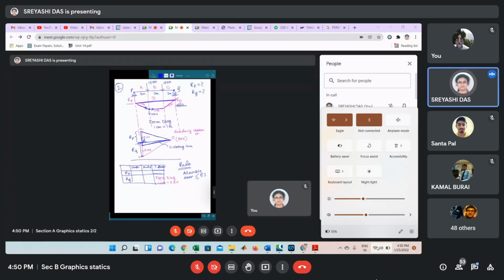Basically, every one of them is a force triangle, meaning each triangle that is formed. Suppose here for this case, take small o, small b, small c. Here the BC force is 10 kilonewton. So BC, we can say this is the resultant of the force BO and OC. Okay, so BO and OC. So here in the form diagram, if we see this BO and OC, and here this is 10 kilonewton.